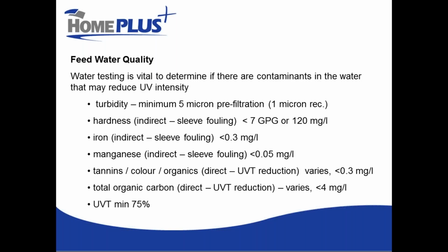Although we don't generally find that that is necessary for operation of the UV unit. 0.05 seems to be just fine with reasonable sleeve maintenance, which we'll talk about.